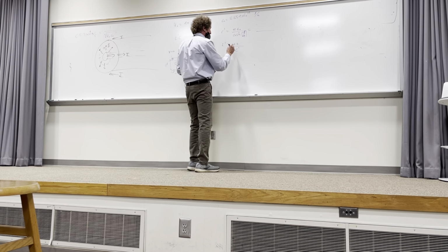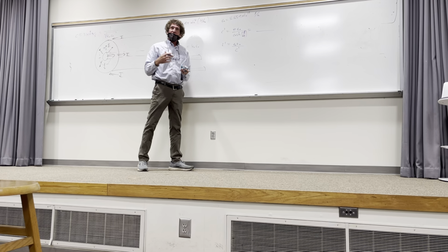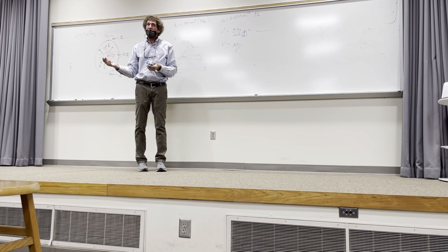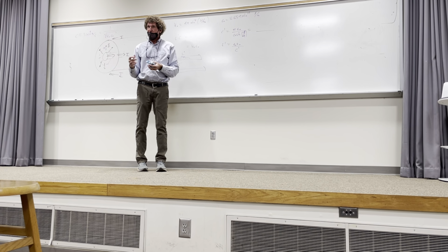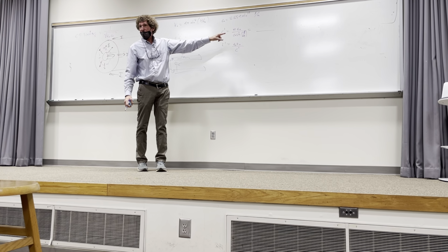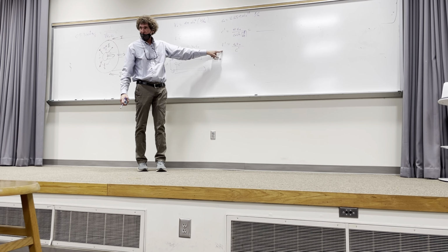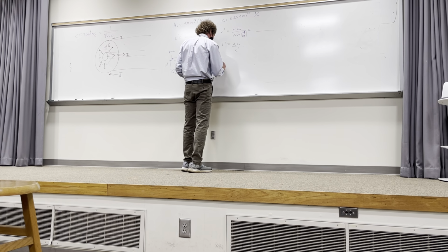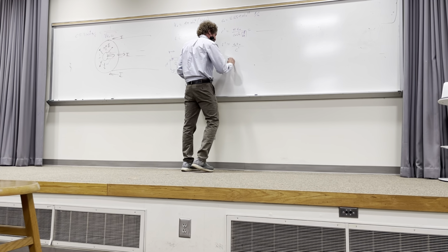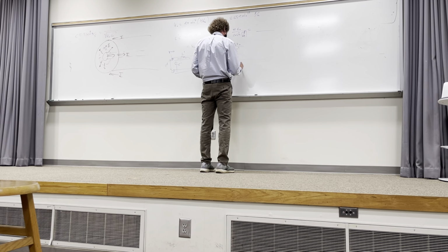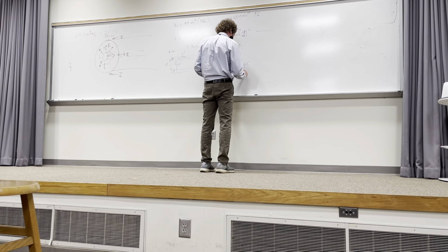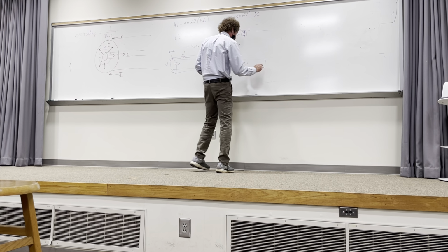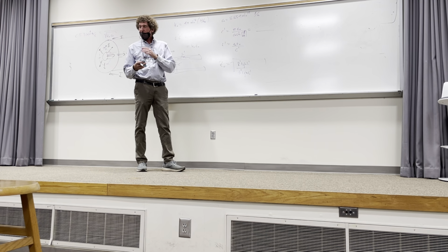Now, once I have that, if I want to get the characteristic impedance, and this is important now, y'all follow me the way I'm doing this. I'm assuming I can nail that. It's a transmission line, therefore I can nail this per meter. You with me, class? So if I have these two things, now what is the actual characteristic impedance, Z naught? Well, technically it's the square root of what? R prime plus j omega L prime over G prime plus j omega C prime, right? That's the technical definition, including losses.